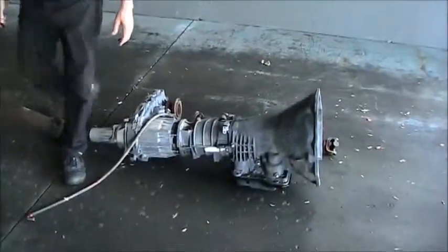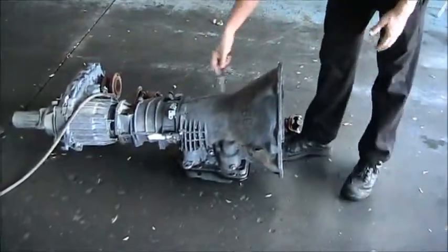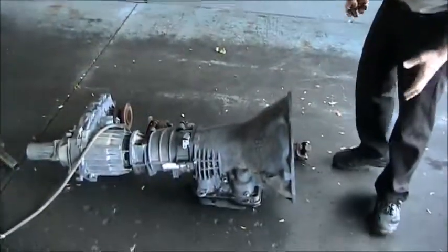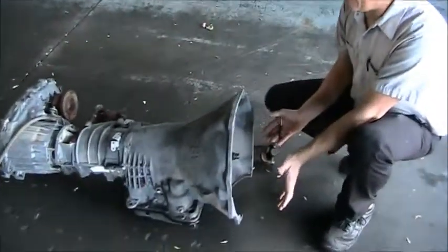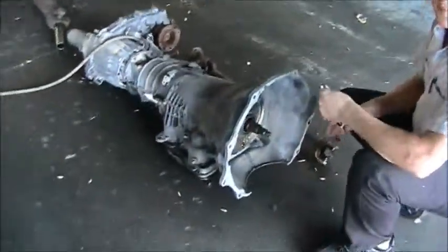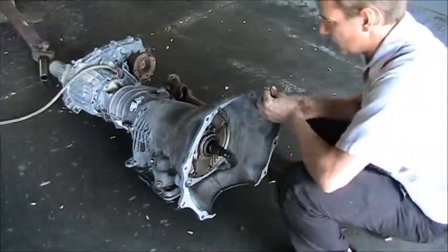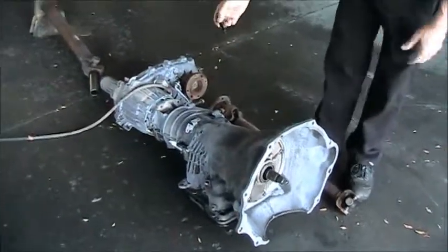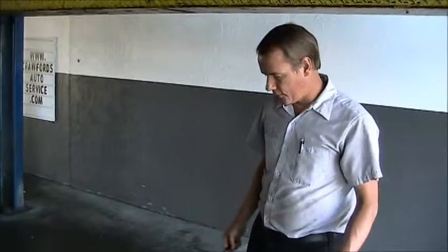We'll start out with the transmission. Transmission is this portion right here. It has a series of gears that go in this transmission. So it has a large torque converter, which is a device that uses fluid to drive the input shaft of the transmission. Then it goes through the transmission through a series of sun and planet gears, again selecting which gear ratio you're in. When you take off, it's going to be in first. As you accelerate, if this is an automatic, it's going to automatically shift to second, then third and fourth.